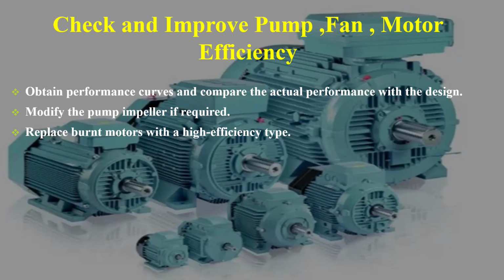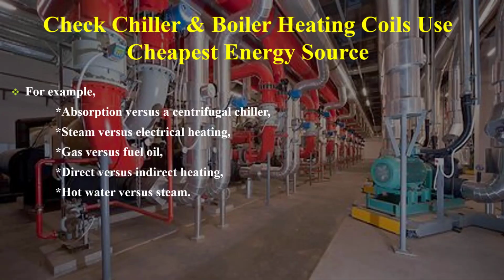Check and improve pump, fan, and motor efficiency. Obtain performance curves and compare the actual performance with the design. Modify the pump impeller if required. Replace burnt motors with a high-efficiency type. Check that chiller and boiler heating coils use the cheapest energy source.